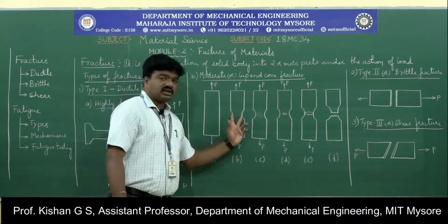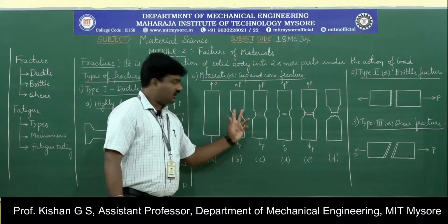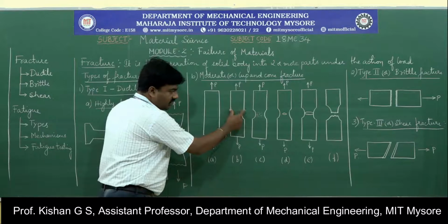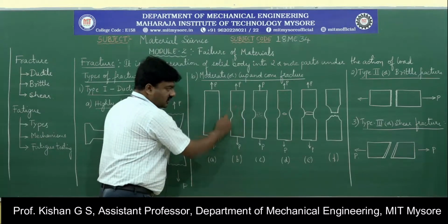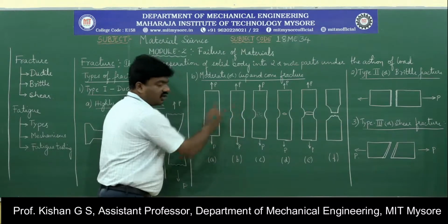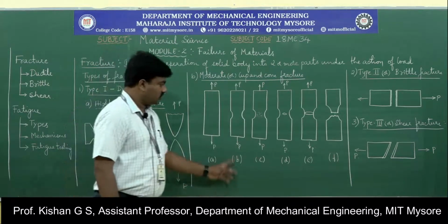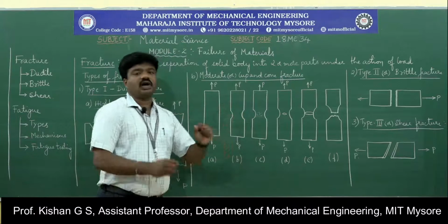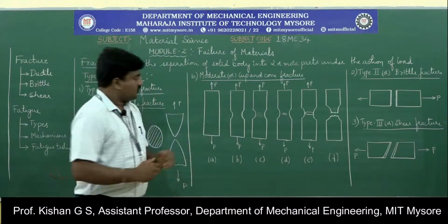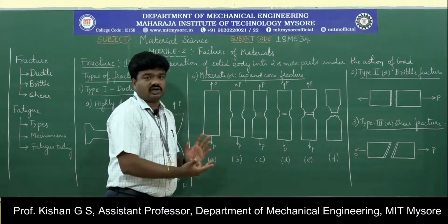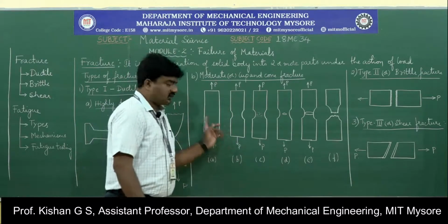will be reduction in the cross-sectional area or the area of the material at one particular point, which you can observe here in this particular profile. This is the reduction in the area or the cross-sectional area of a specimen which is observed in stage B. This is a result of application of load. For the same specimen, upon further increase in the loading condition, we are going to consider